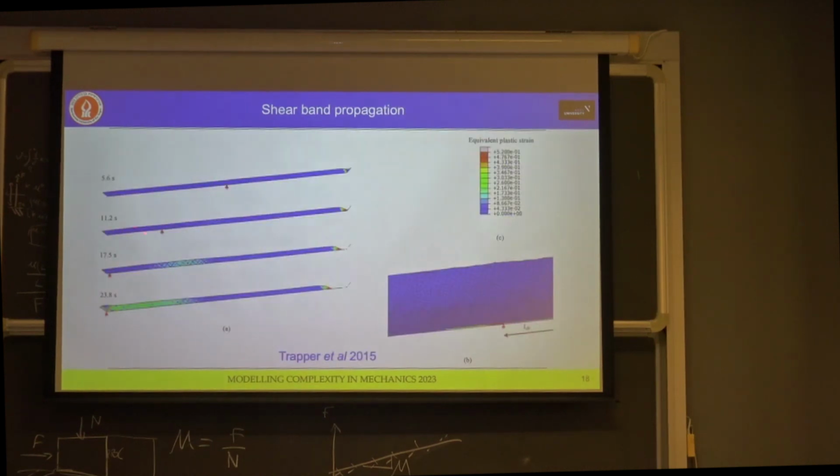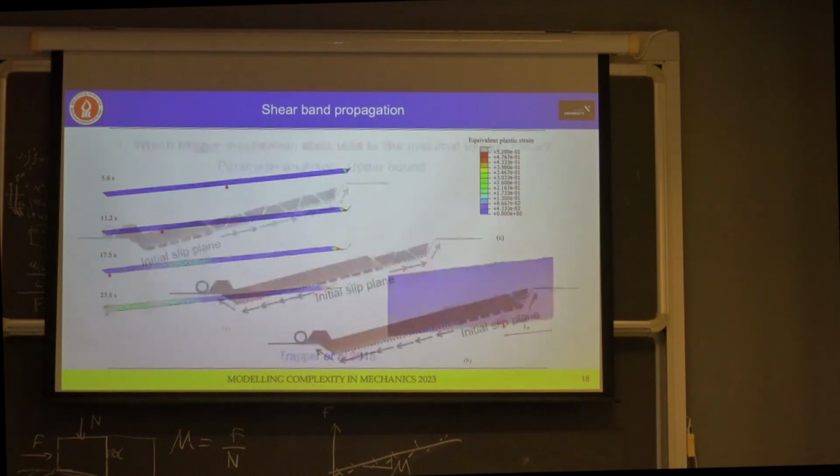Okay, so if we look more closely into the landslide, we have here the shear band, so we have the failed soil, and then on the tip of this shear band we have some soil that is on the way to fail, but we see that it's concentrated within one element width. It can be mirrored later, but on the tip it's usually within one element width.